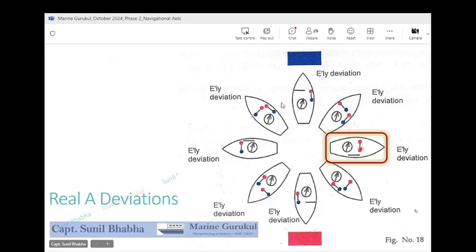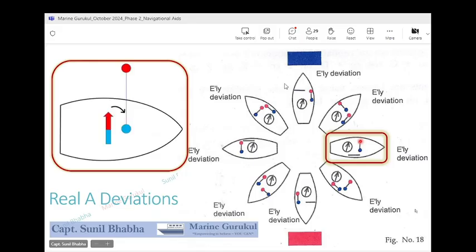On the other hand, the outward ship beam is now perfectly aligned with the magnetic field of the Earth, thus generating maximum deviation. So let's now zoom into the easterly heading diagram and see the effect in detail. You can see the outward ship beam shown in the diagram. I have taken the outer end slightly outside the ship structure to make it more clear and easy for understanding. The fore and aft longitudinal is not shown in the diagram because there is no induction and no poles are generated.